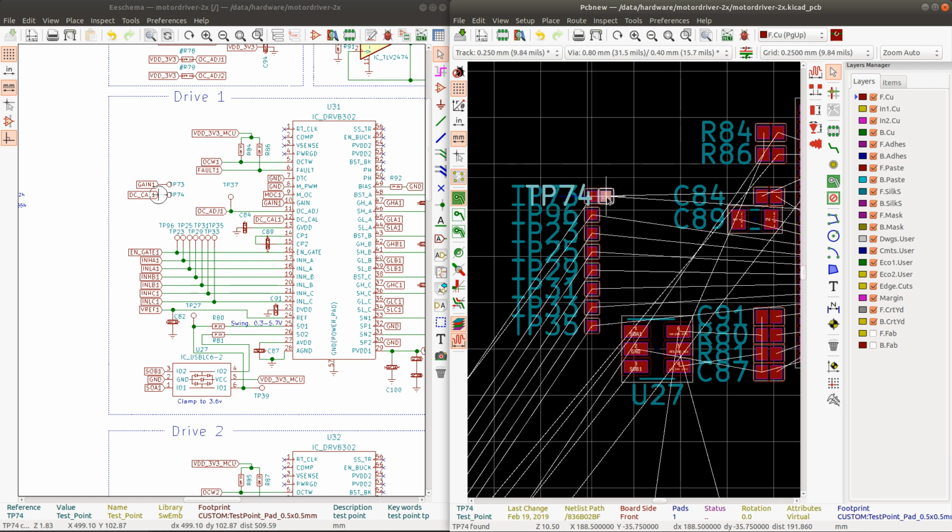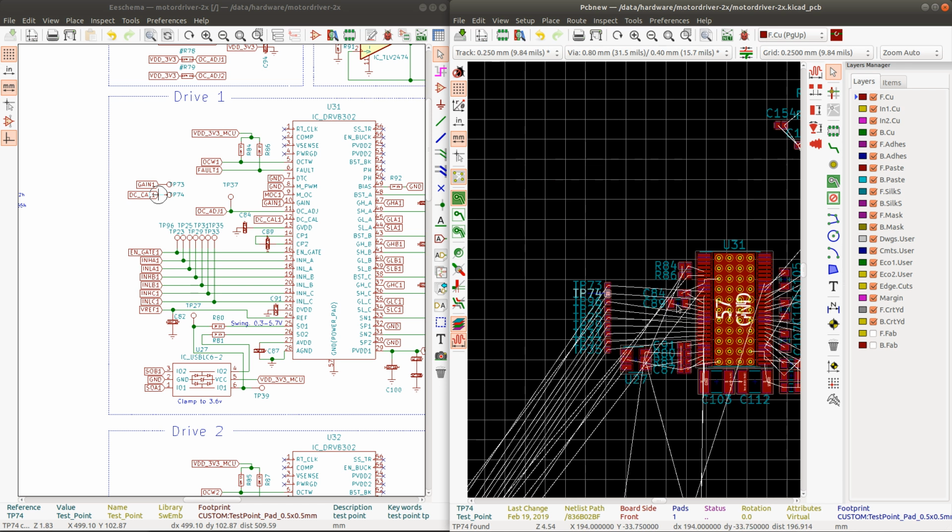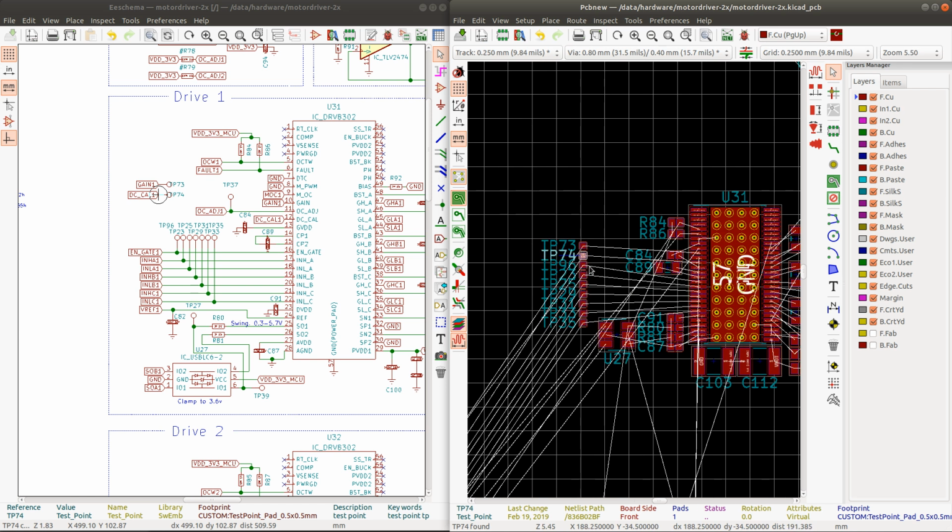And for that, you can use this DC calibration input to put this current sensor into a kind of DC offset measurement mode, which just outputs the DC offset on the current outputs. I think what it does is it disconnects the stage. So essentially you get the 0 point. And then you can measure that 0 point, save it in the software, and use it to determine the exact current.